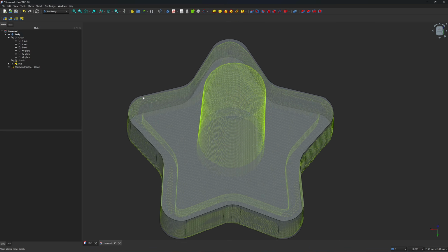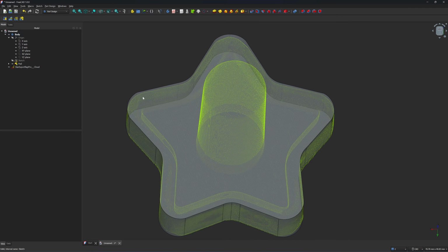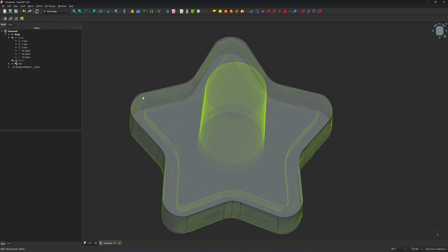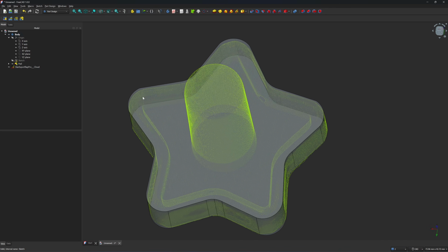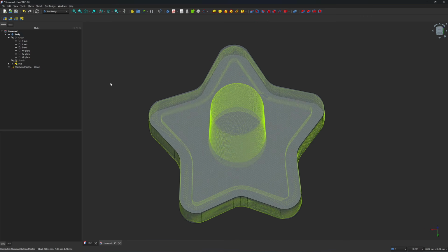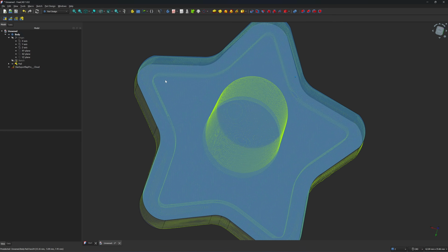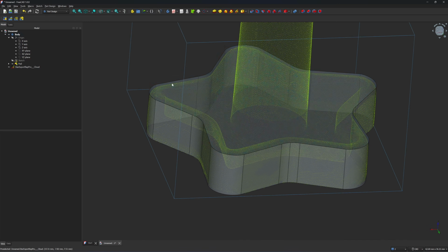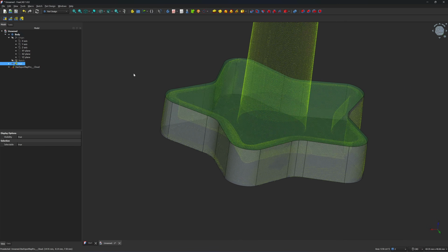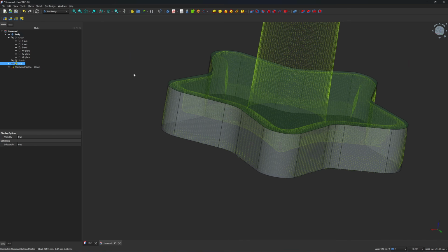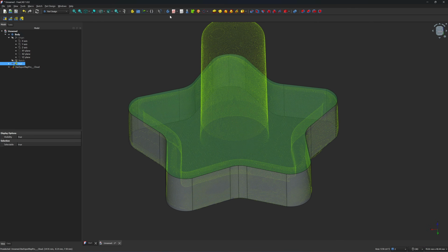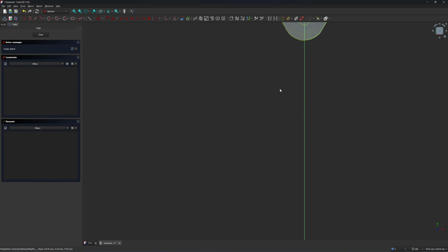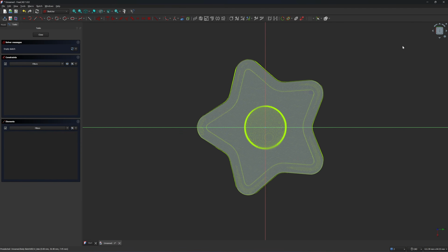And number two is that when you mesh the 3D scan, the software will apply smoothness, and that is when you lose the accuracy. Okay, next I'm going to cut a pocket inside here and create a wall. So I'm going to create a sketch on the top here. I click on this plane first because I want to create a sketch on this plane, and then I click on the sketch command. So now we have a sketch. Click on the top view, right?